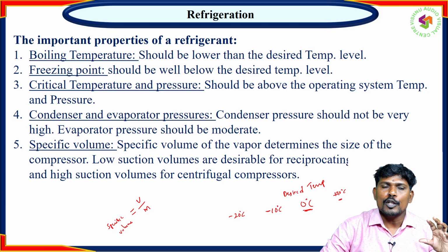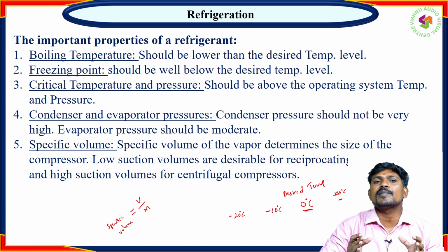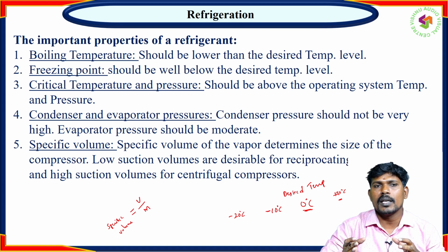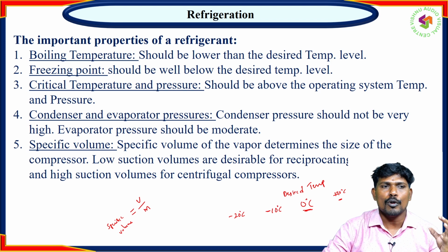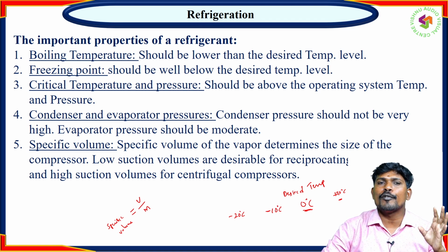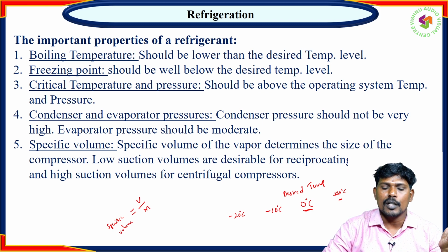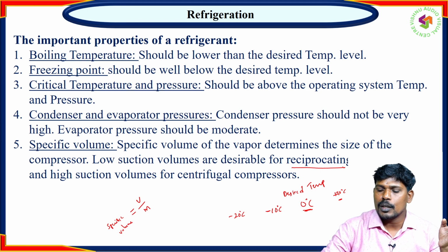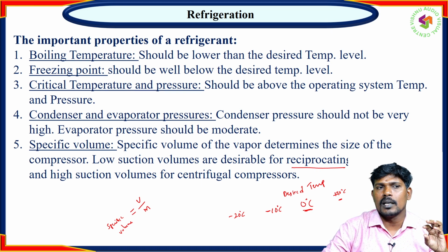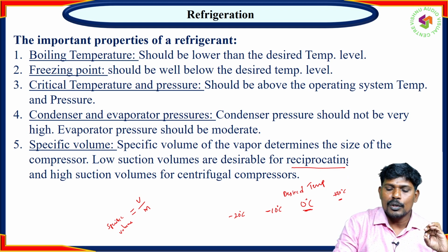Okay, means the specific volume decides what is the size of the compressor. Okay, so whatever the refrigerant you invented or you want to choose, if the specific volume of your refrigerant is very high, then you need to choose the reciprocating compressor. If your refrigerant specific volume is less, then you can go for the centrifugal compressors.